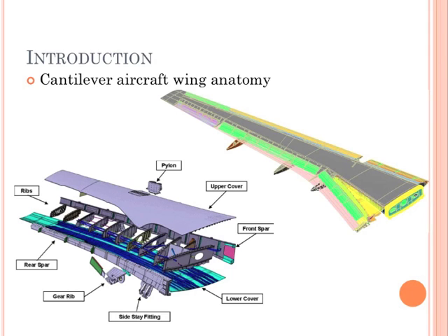These are just pictures of a conventional cantilever wing structural design, which is also called a wing box. The structure has forward and aft spars, rings, ribs, and top and bottom skins, and typically the volume between the ribs and the skins is used for fuel storage.